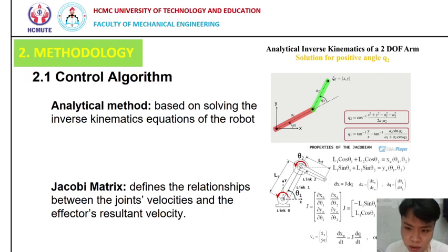In the picture, we have a manipulator at a position x and y in an xy coordinate system, and we determine x and y and move the manipulator to that coordinate by solving the inverse kinematic equation, and we will find Q1 and Q2.